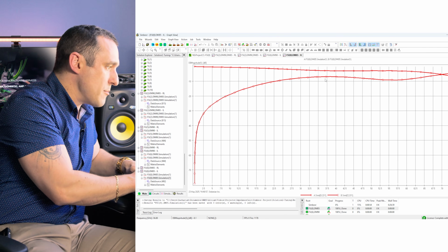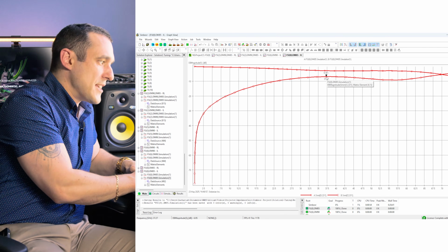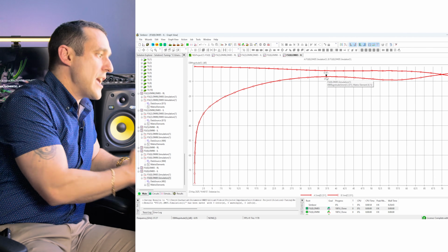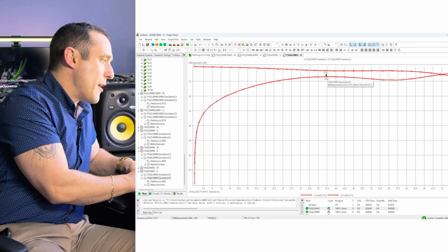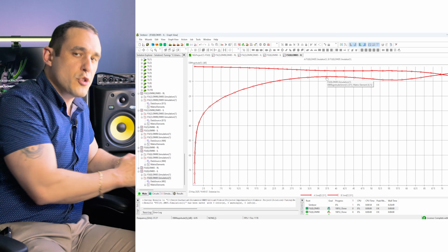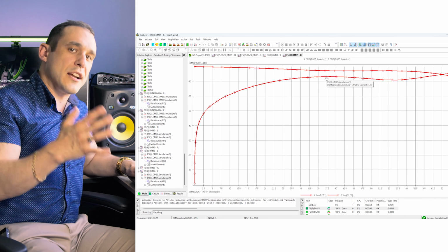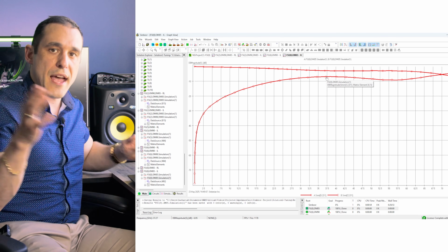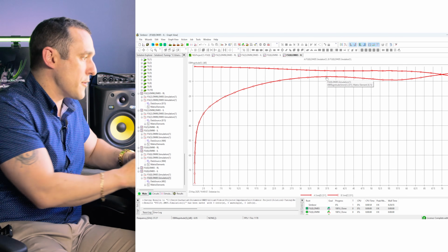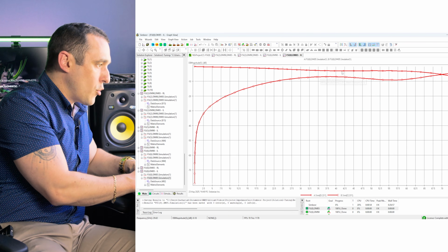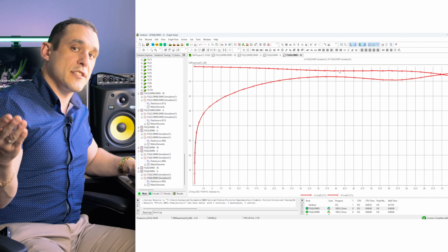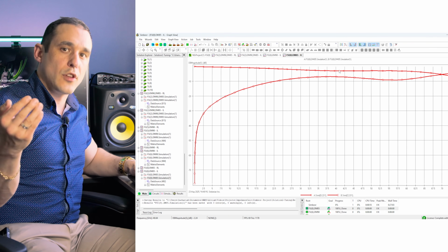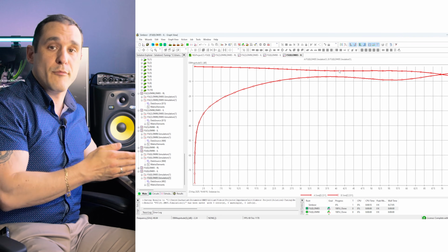You can see that the peak mode conversion is just a little less, about -7 dB or -6.87 dB here at the peak, around 37 gigahertz. So you do get mode conversion, but not as bad as in the previous case where we had the traces initially spaced close together. You can also see that this corresponds to the dip in the insertion loss curve, and so it also explains why you get greater loss in the differential mode when you have mode conversion.